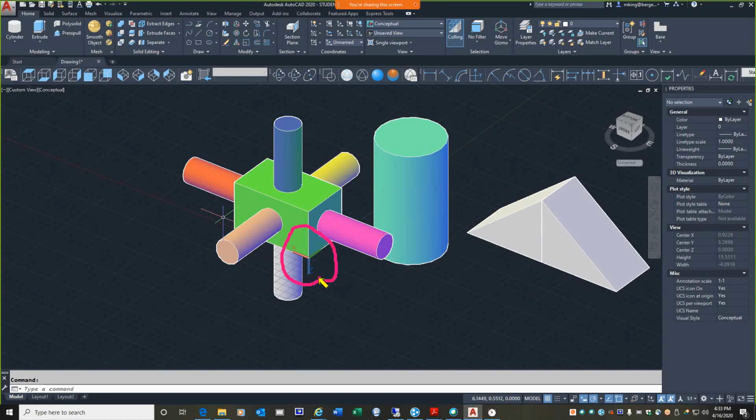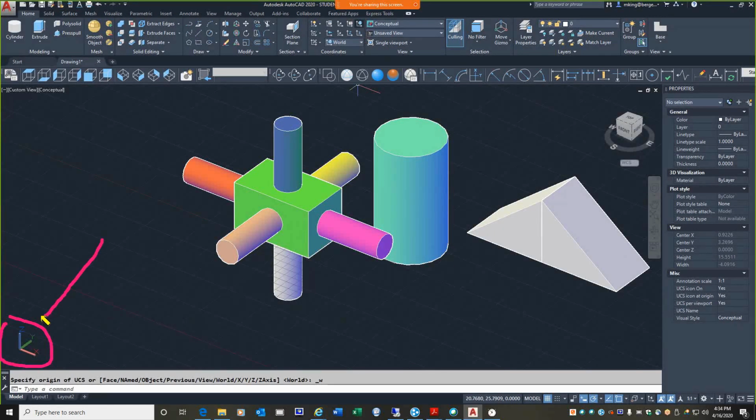So what if I want to reset this coordinate system back to what it was originally? That is what's called the world coordinate system. Right above the 3-point is the world system. It's got that little icon of the Earth there. And this is the easiest one of all to use. Simply click that button. And when I click that button, my coordinate system returns to its original state, right, where the ground is what it used to be and up is up and so forth. Okay? So when you want to reset your coordinate system, it's one click away with world.